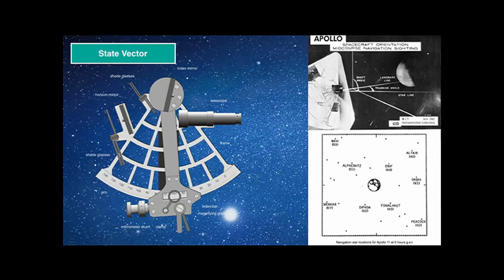The whole optics hardware in the command and service module can be moved to point in the general direction of Earth or Moon. With the launch of program 52, we command the Apollo guidance computer to rotate the spacecraft to point one axis of the sextant, the so-called landmark line of sight, LLOS, to the nearest body, which is Earth or Moon. The astronaut then uses the optics systems to exactly align the horizon to the LLOS. With a telescope, the astronaut looks for one of the known stars, points the star line to it, and lets the Apollo guidance computer read the trunnion and shaft angle. Repeating this one or more times in a different plane gives a three-dimensional position of the vehicle in space.